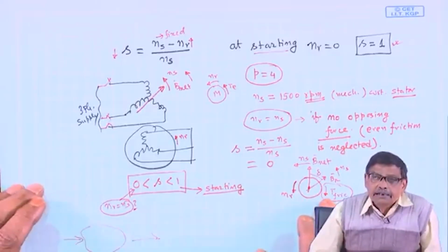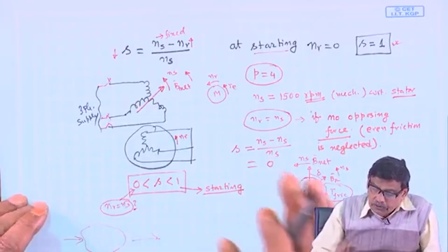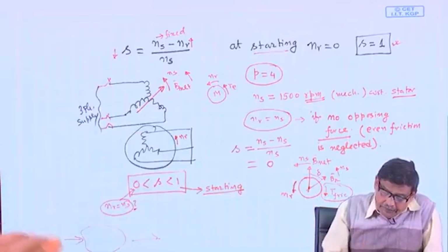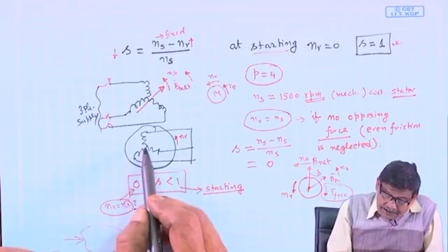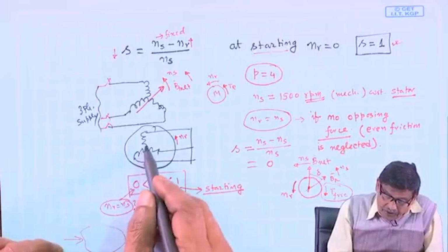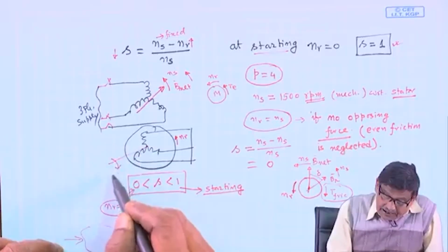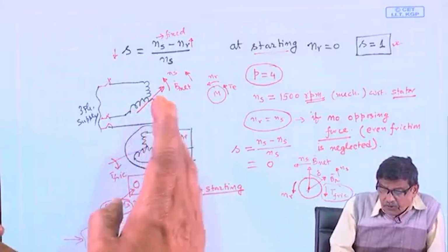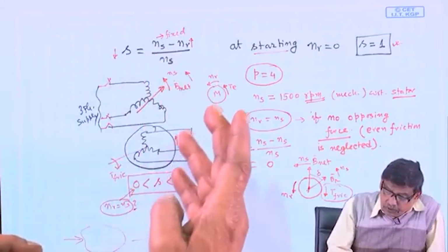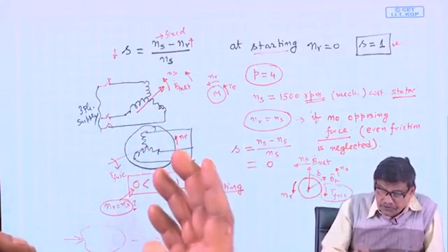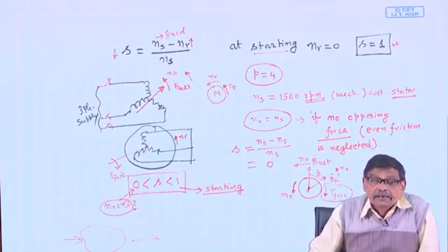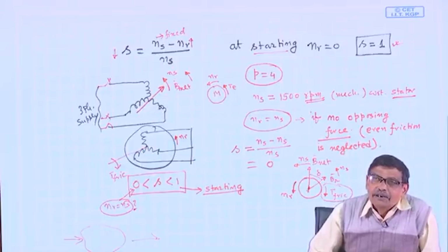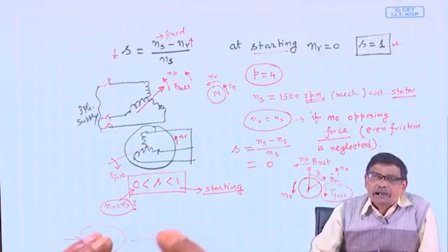Similar thing here. You energize the supply and there is some opposing frictional torque acting in the opposite direction, and you know there is a stator field, there is a rotor field, the circuit is closed, electromagnetic torque is there, but this electromagnetic torque must be greater than T friction, so that the drama begins.